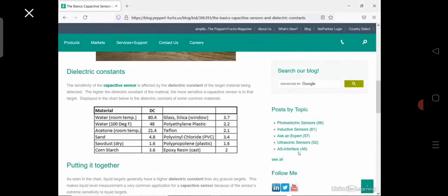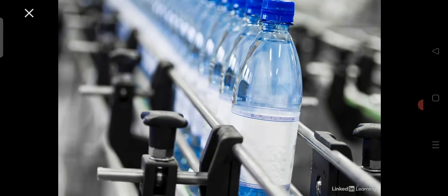Here is a reference showing a chart with dielectric materials, and on the right side of the chart are some common materials used for containers that would allow the sensor to see through. So now, one of the considerations when using capacitive proximity sensors is to keep in mind the sensor sensitivity to humidity, moisture conditions, and varying temperatures, so the overall conditions matter when designing the system.